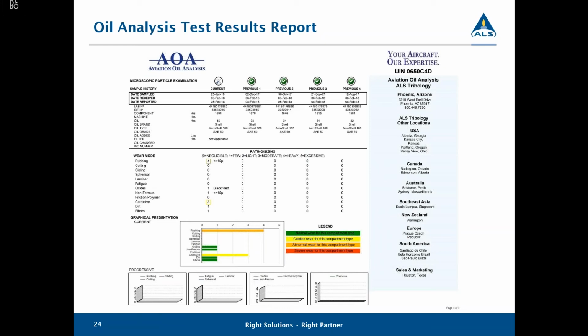Once the MPE is done, we do quantify these. So while we do a visual inspection and a visual diagnosis, we then at least quantify it as well, and we'll put it into this historical pattern. MPEs were not run on the past samples because they are normal. I don't really highly recommend doing an MPE on samples that are normal. While you do get a lot of valuable information when there is an issue, it's a little overkill when you're doing normal sampling. So regular standard basic oil analysis is great for those normal samples.